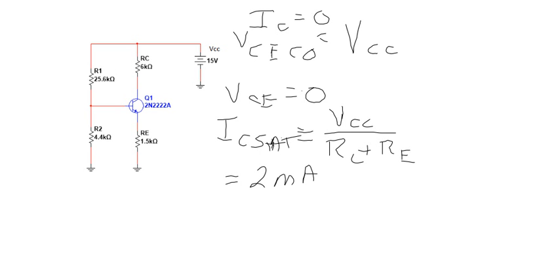And by choosing a base voltage now, which I believe I've done correctly, we'll find out in a minute, I want my actual operating point to be about halfway in the middle of my load line.